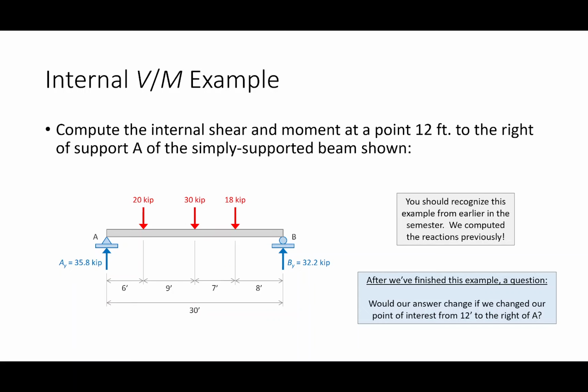So what happens if I take the integral of 0? I get a constant, because the derivative of that constant is 0. So between here and here, I'm going to have a constant shear, and I'm going to have a linear moment. Does that make sense? So we're going to start slow and work our way up, but we are going to address some of the situations you're talking about.